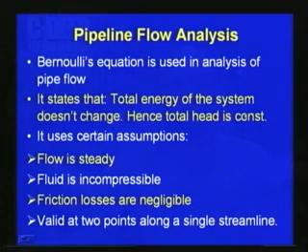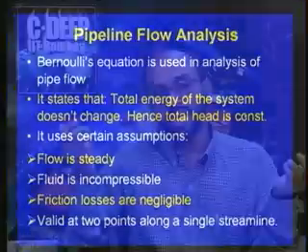So, for a given system, when we design a pipe, we can first check what data are available and what is to be determined. Accordingly, we can classify whether the problem is type 1, type 2 or type 3. Then we can see which approach we have to utilize, whether we have to go for an iterative procedure or whether the solution is straightforward.